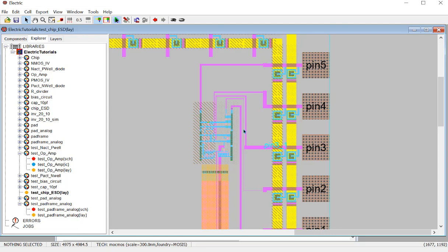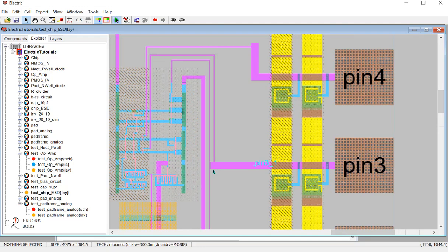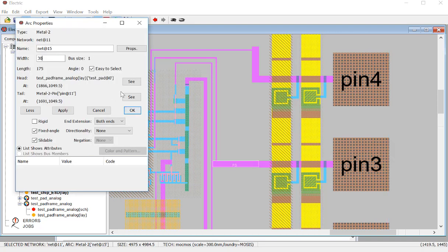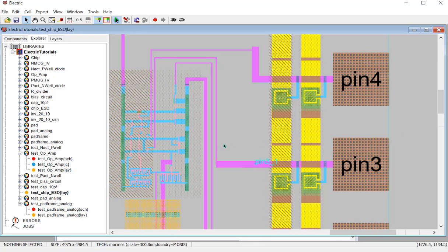You can modify the width of these wires if you like. It's not actually mandatory if you don't want to do that, which is fine. But for here, it's too close. But the thing is, it's DRC clean, so it's actually not a problem. But I still want to change it. I don't want this one to extend to both sides because that looks weird to me. And then I5 is still clean. So you can see it's not really hard to make it work actually.